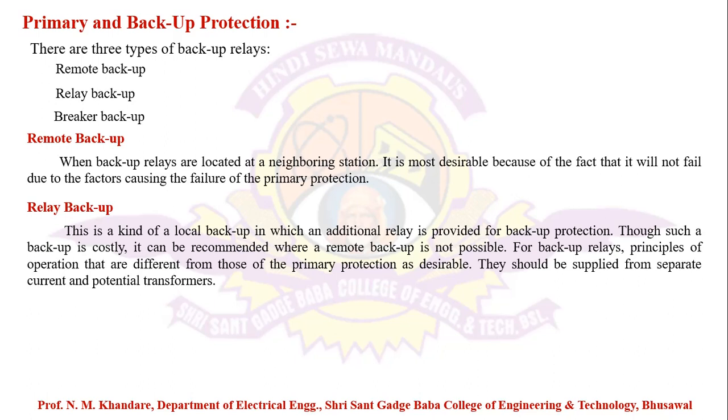This is a costly system because for those relays we have to provide separate CTs as well as PTs. Along with that, we are also taking one important precaution: the secondary or backup relays must have an operating principle different from the primary relays, because whatever causes are not operating the primary relays, if we provide the backup relay with the same operating principle, the same factor will also affect the backup relay.